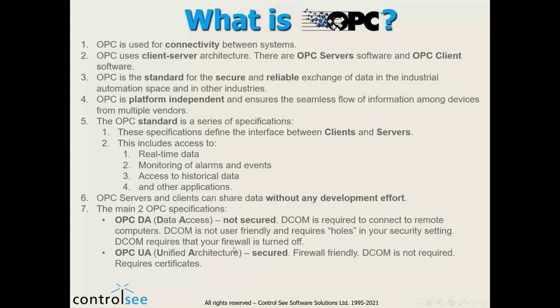The newer specification is OPC UA, which stands for Unified Architecture. And this protocol is secured and firewall friendly. It can work over a firewall, and DCOM is not required at all. It requires certificates.